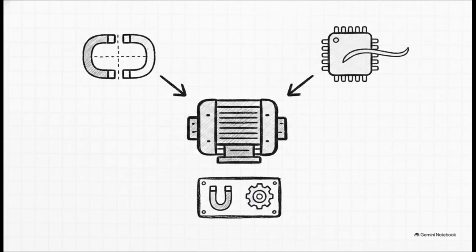So, let's summarize the sheer engineering brilliance of analyzing machines using DQ windings. First, we achieve zero magnetic coupling between our control axes. Second, this yields radically simpler mathematical expressions that our microcontrollers can actually process in real time. And third, the ultimate prize, we gain completely independent control of the air gap flux, which is handled by the D-axis, and the electromagnetic torque handled by the Q-axis. We've literally turned a complex AC motor into a highly controllable DC motor equivalent.